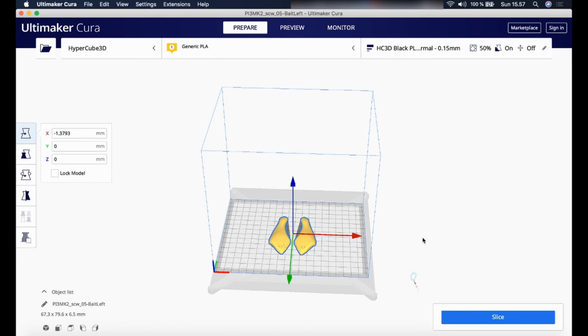Okay, next I will slice it. My slicing parameters are so that I set the generate support on. It may or may not be necessary. I found that it's quite easy with my printer to remove those generated supports, so I will just use it. It will help to have nicer cavities. So I will slice it now.